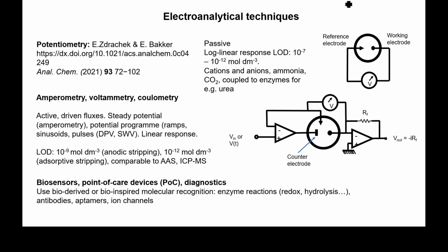There are also biosensors and point-of-care devices and diagnostics, which can fall into either of those categories, but I put these up as a separate category because they have an awful lot more engineering that has to go into these, but they're typically using bio-derived or bio-inspired molecular recognition, such as, for example, enzyme reactions, redox hydrolysis, or recognition using antibodies that we've generated and then created with hybridomas, aptamers, which is the latest game in town, using longish single strands of DNA, typically DNA, although RNA and proteins as well, typically around 20 to 40 bases long, or even ion channels that we've cloned and cultured.